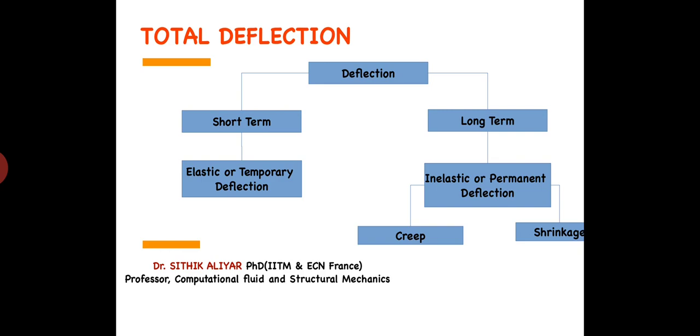When you construct a water tank above the building, everything looks good, no problem at all. After 1 month, after 1 year, you see cracks below the water tank at the top in most of the buildings, because of the heavy load over time. The crack developed because there was a deformation. That deformation is called creep deformation.